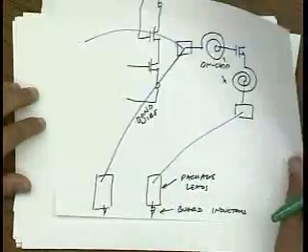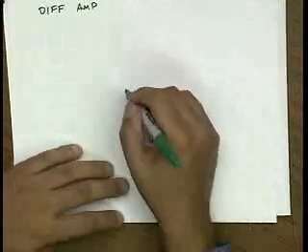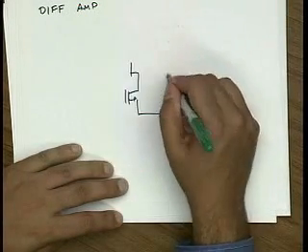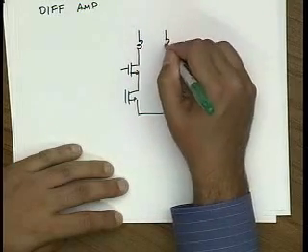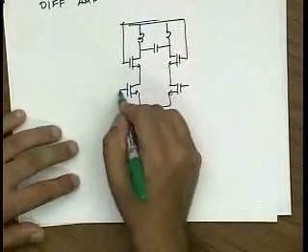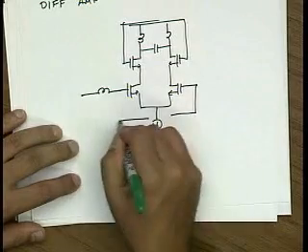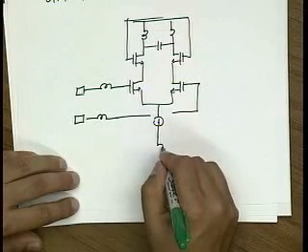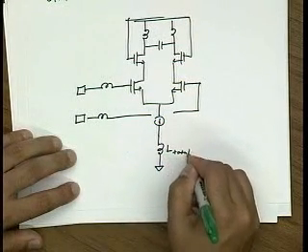Another option is to build this amplifier differentially. So let's look at that and why that helps. A differential version of this amplifier looks something like this. Again, we're going to use a cascode topology. We're going to use some on-chip inductors as the load. And I can use some on-chip inductors for the gate here. And then this is going to come to a couple of pads. And this here goes to ground. So this is the total inductance to ground.